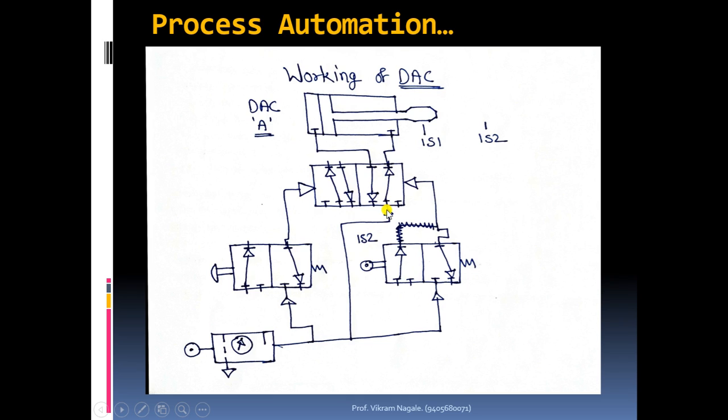Input given at 1 will be given to 2, and since the valve ports are connected right to right and left to left, and the line is transferring the air from the input side to the output side, that air will be given to the right hand side of the piston. Whenever that happens, if the piston is on the extreme right side, it has to move towards the left side.